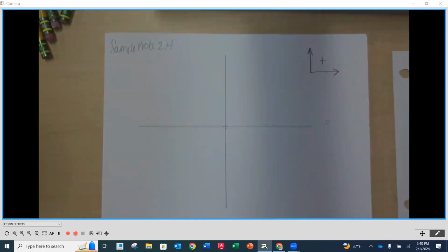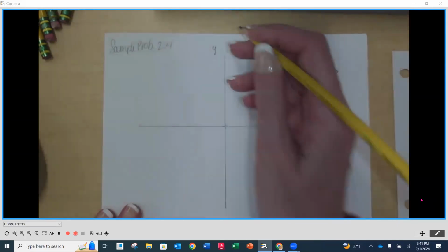This tells us what's going to be positive in the X and Y direction. So when we write our equations of equilibrium, we're going to know that anything pointing to the right is identified as positive. Anything going to the left is identified as negative. Okay. Now we've got our axis system. We know this is our positive X, our positive Y.